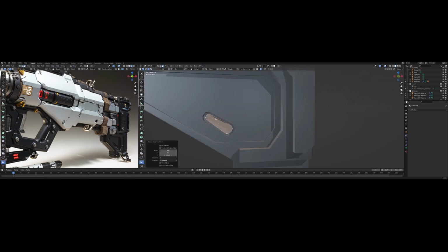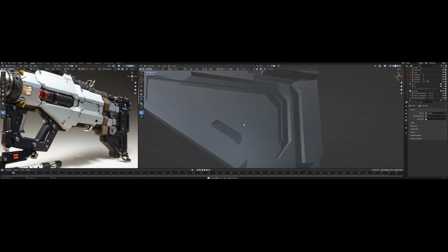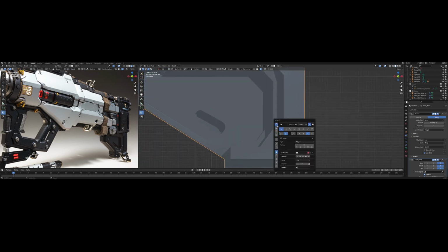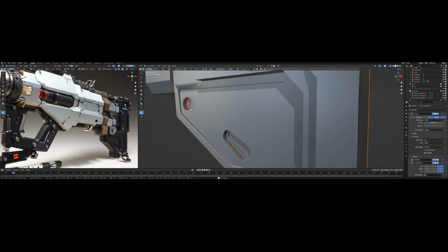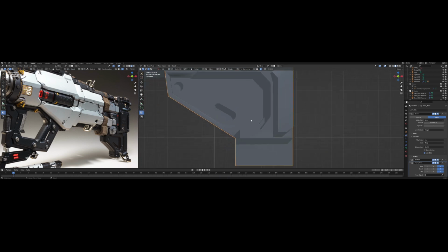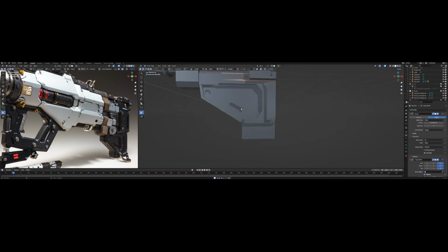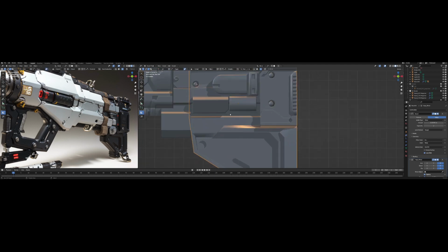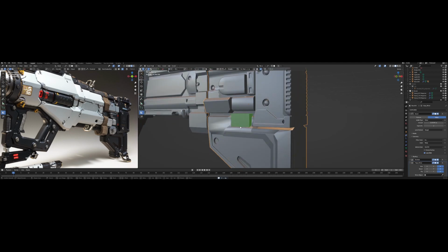As for those small rounded parts on there, it will also be pretty easy. Just directly use the cutting knife with the cutting boolean, press B to go to bevel, and make the shape look like the rounded one.